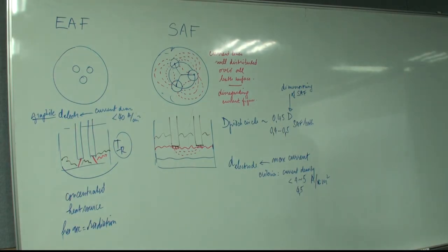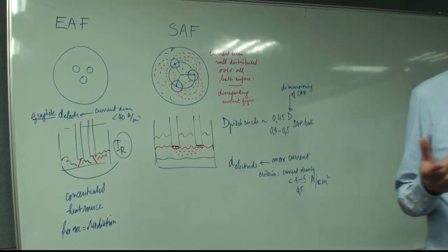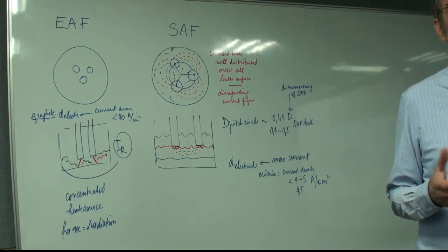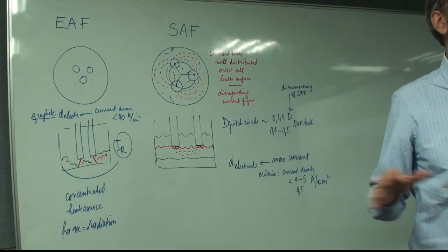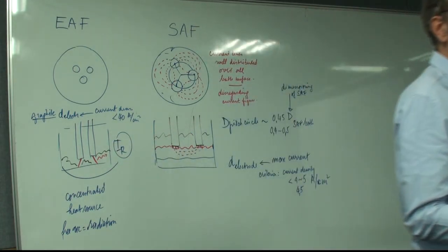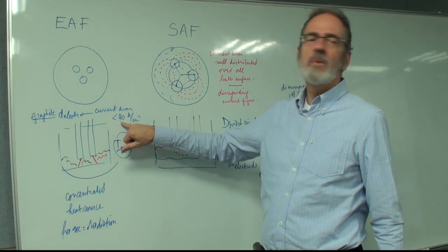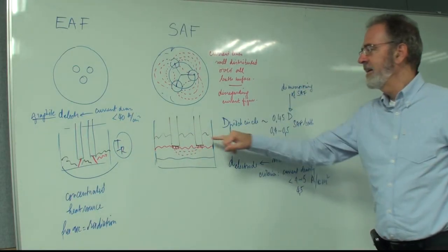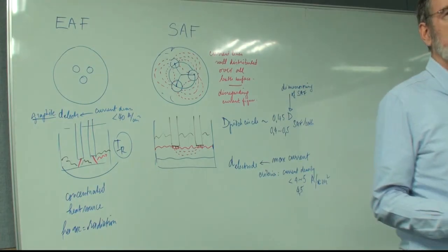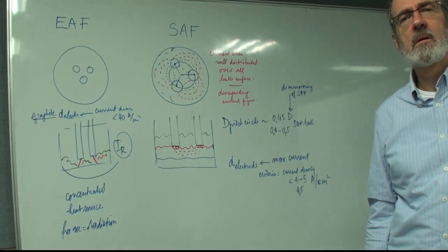In case of graphite electrode, the current density is different depending on the diameter. No, the current density is defined as the current divided by surface. But of course, graphite electrodes, which are baked at more than 2000 degrees, withstand much higher current densities than these self-baking electrodes. In our case, in Gwangyang Bio plant, we can use the graphite electrode.